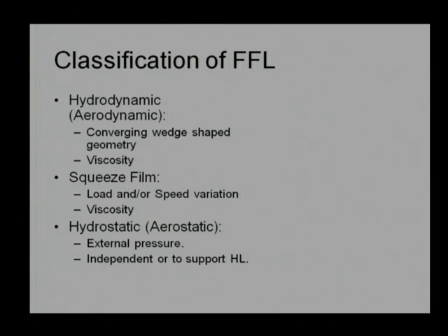Both of these mechanisms require two things. One is that there should be some viscosity. If viscosity is 0, then it will not occur, or we say a solution will not be obtained using conventional equations. Another thing is a converging wedge shape. There should be a convergence, some inclination, a gradient which makes the hydrodynamic or aerodynamic action or mechanism.